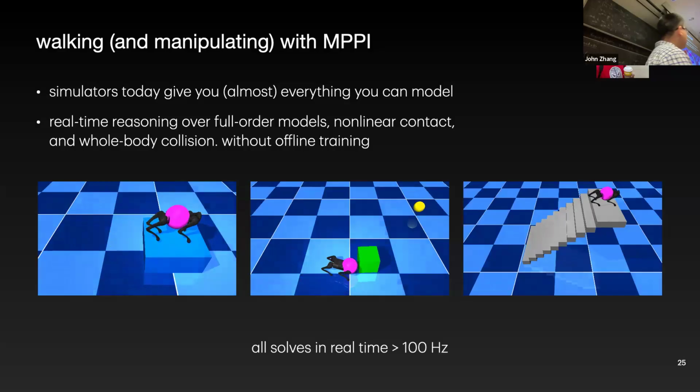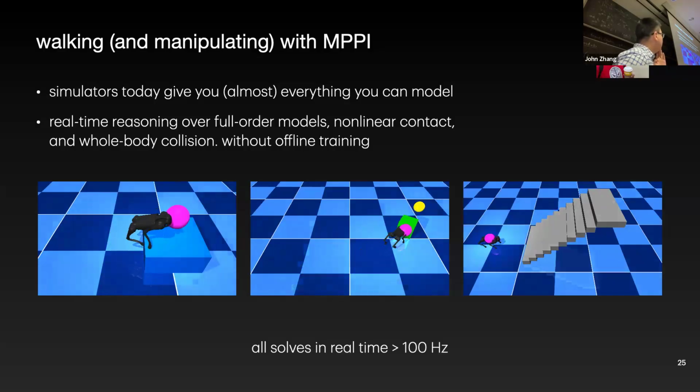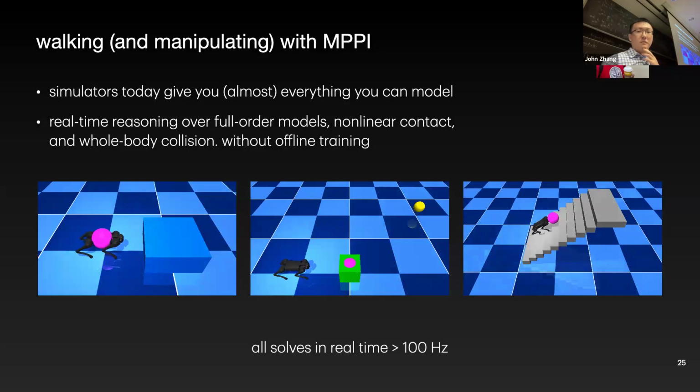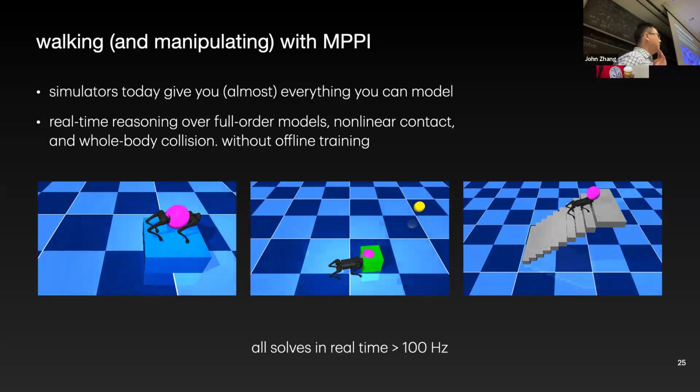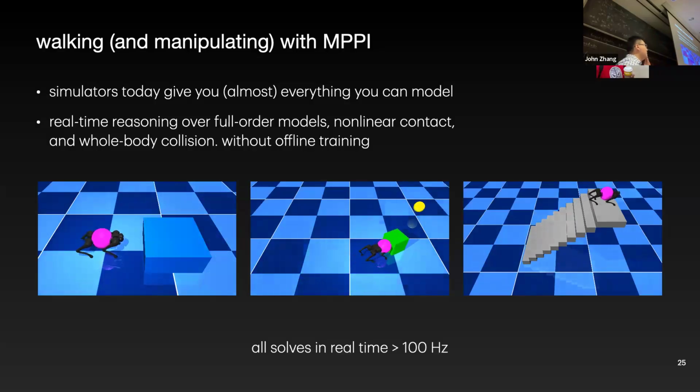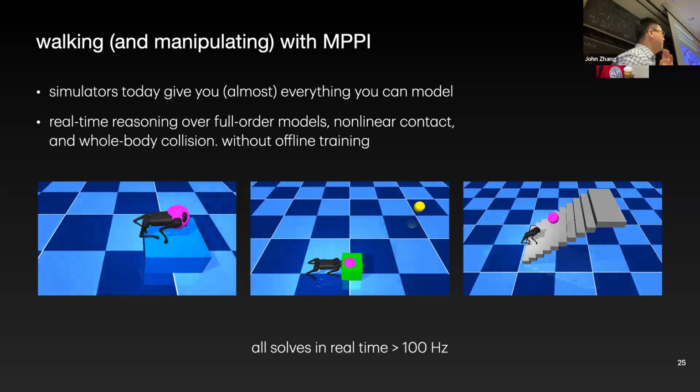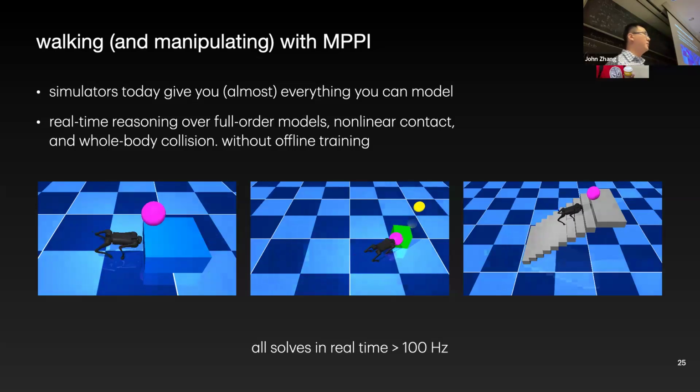In the first task, the robot starts off a little further away from the box, first it's flying, and then it gets closer and closer. At the point where it first attempts to climb, in that sampling horizon, you would have to sample a little bit above to make the move. So you would never have sampled there before. How does the covariance matrix evolve? Yes, that's also a good question. We're not updating the covariance matrix. For different tasks, I think we tune the covariance matrix manually to encourage exploration a little bit, but we're not doing anything smart with regard to updating the covariance matrix, that sort of thing.